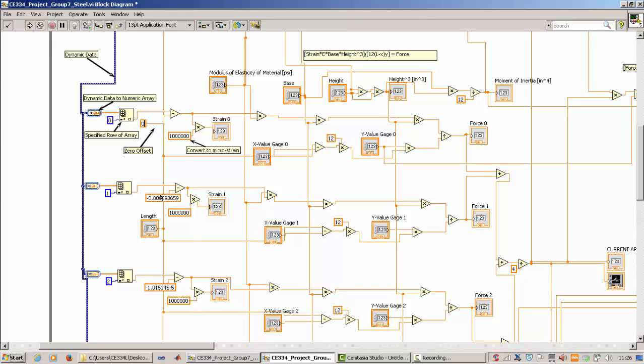And then once we see what those measurements are, we're going to take those and put them into the 0 offset. That way we can specify where we want our 0 point for our experiments to be. So I'm just going to undo that, put it back. Okay, so that'll take whatever value it's getting and subtract this value so that it'll put it at 0 where we want it to be 0.